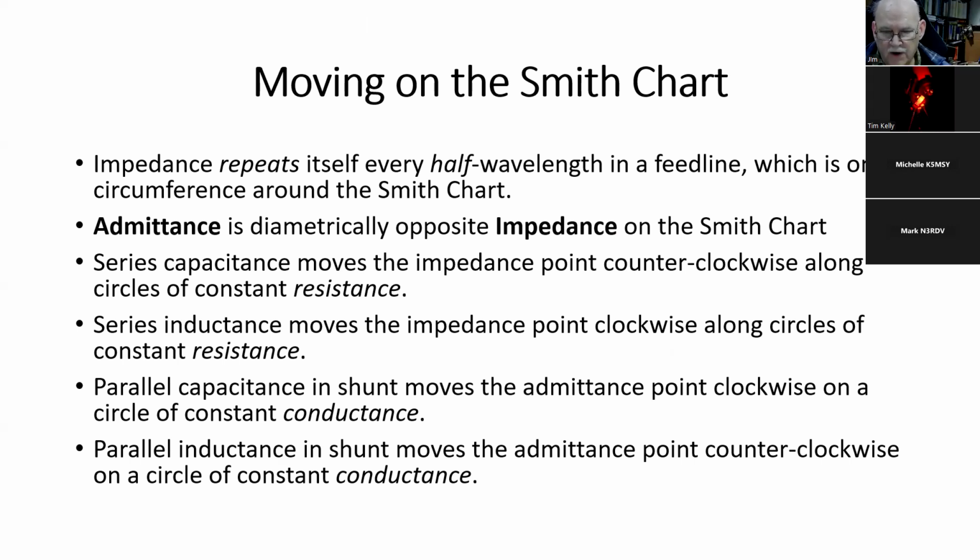And if you think about admittance being the inverse of impedance and conductance being the inverse of resistance, that makes sense. Parallel inductance moves the admittance point counterclockwise, again on a circle of constant conductance. And these are powerful things to know that we can use to develop matching circuits either on a paper Smith chart or electronically, as I'll get to.